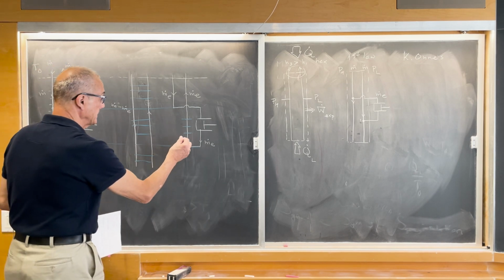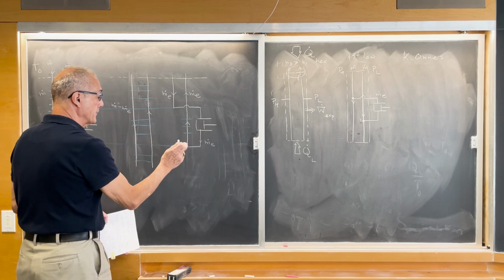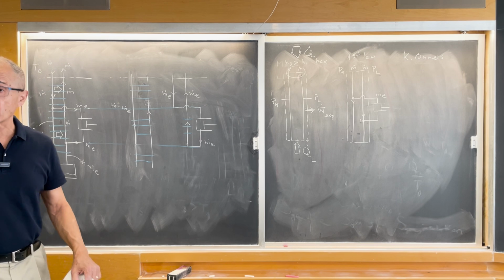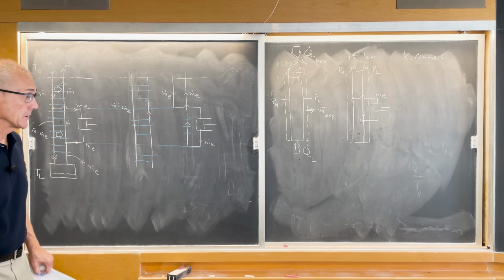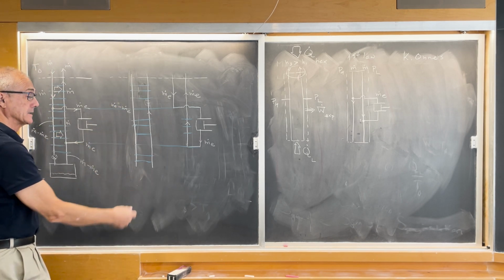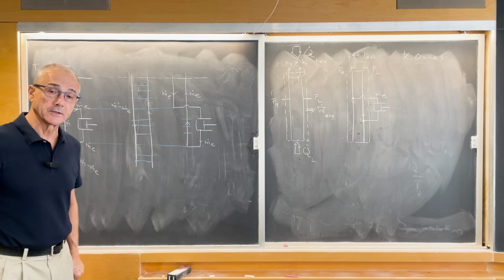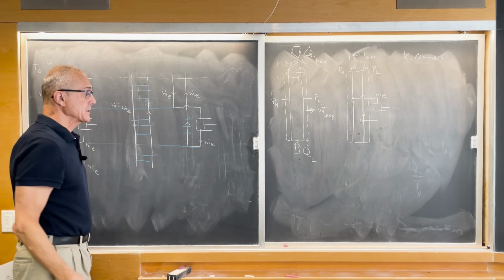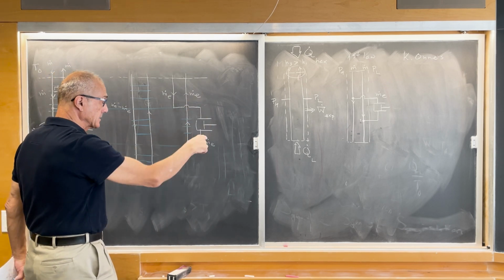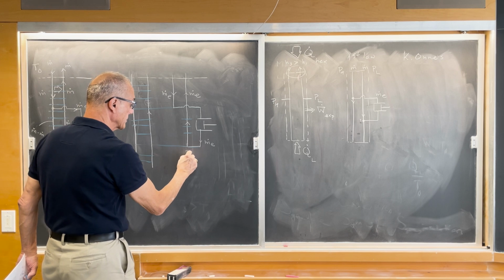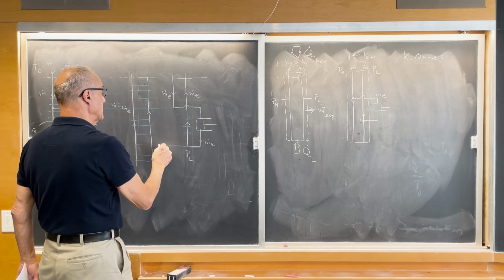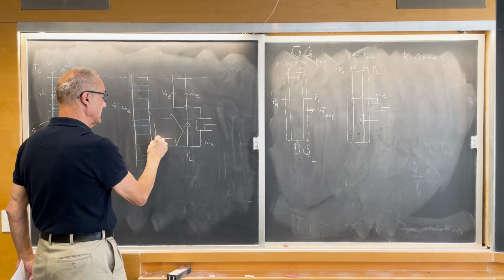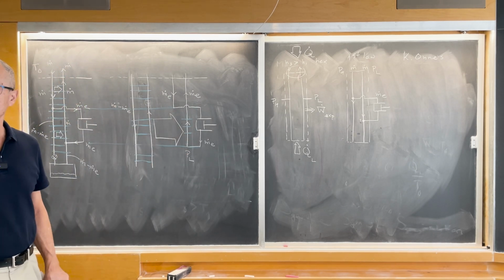This particular stream, to go from here to here, must be warming up, because this vertical track is the track between cold and warm. So the extracted stream, while at low pressure, is being heated by the balanced counterflow.